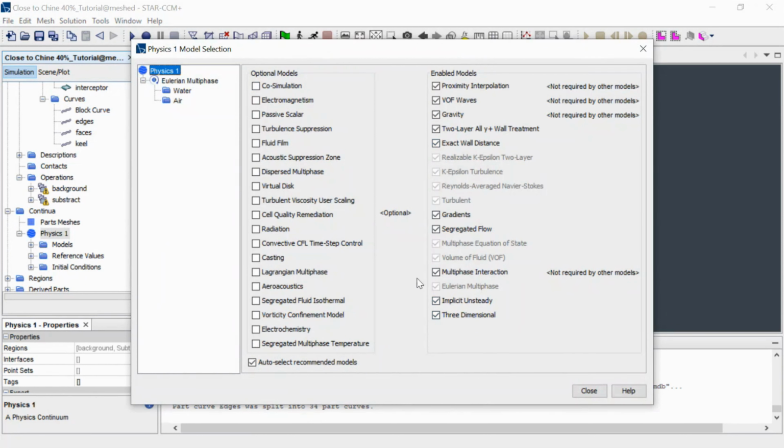Assuming that the waves are propagating steadily without change, this is the steady wave problem. The wave trains can be uniquely specified and solved in terms of three physical length scales: water depth, wavelength, and wave height. The volume of fluid model is for systems containing two or more immiscible fluid phases, where each phase constitutes a large structure within the system, such as typical free surface flows. This approach captures the movement of the interface between the fluid phases and is often used for marine applications.